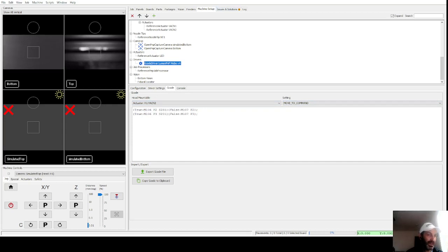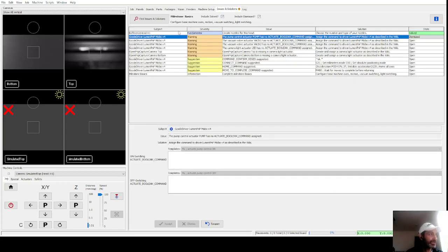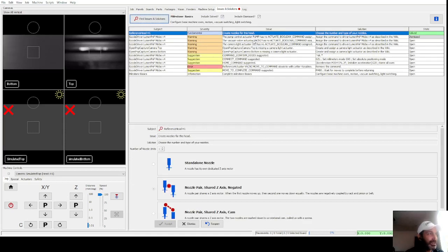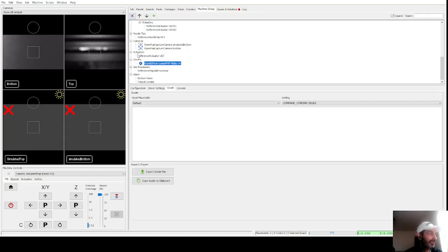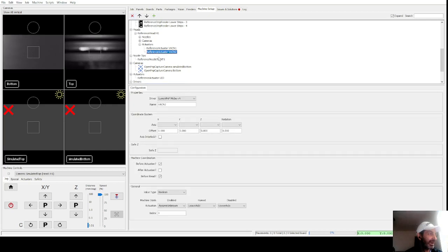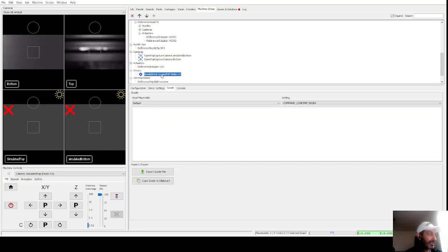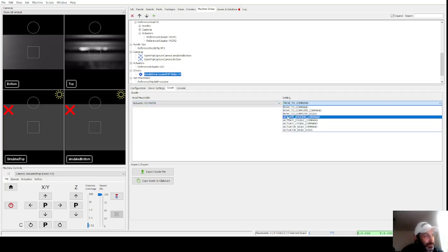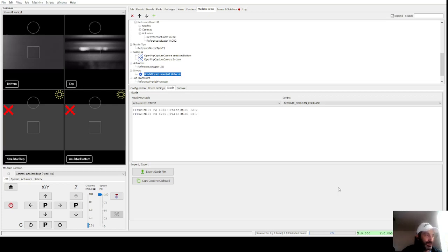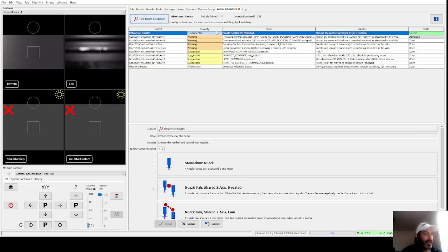Let's go back to issues and solutions. Let's apply it. Whoops. Go back to issues and solutions. Find. That disappeared. We have vacuum has no actuate Boolean command. Thought we did that. VAC N2. Let's check it one more time. Expand VAC N2. Nope. Here. VAC N2. Oh, I put it in move to. Shame on me. Boolean command, that's the problem. And we'll apply. And we'll come back over here and we'll refind, and that disappeared.